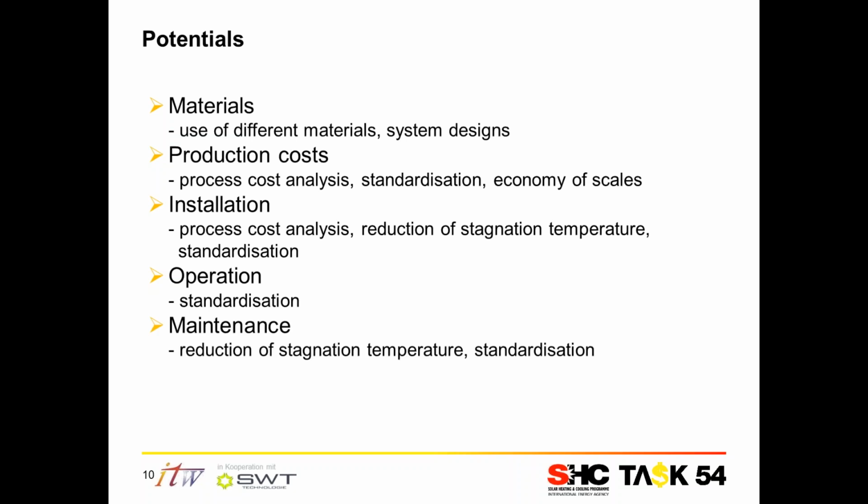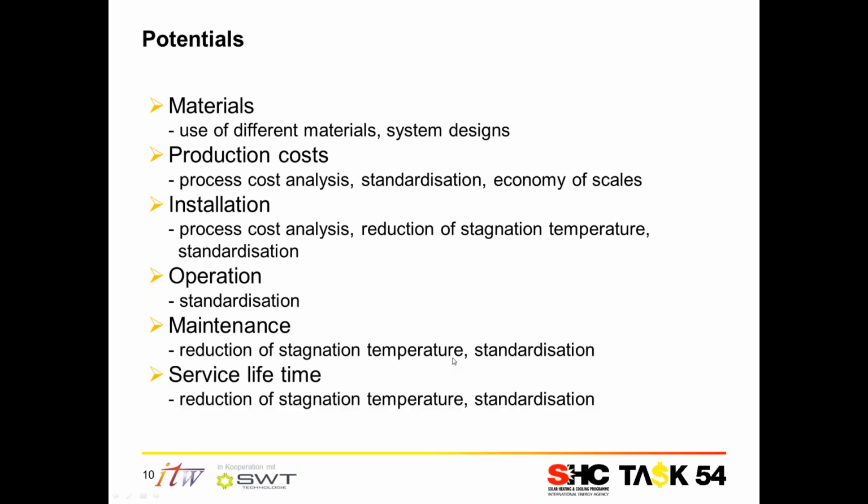The reduction of maintenance can be achieved by a reduction of the stagnation temperature again, and also with standardization, because the installation is error-free if we have a high degree of standardization. And last but not least, the service time life can be extended, which also leads to a reduction of the levelized cost of heat. And here, the reduction of stagnation temperature as well as the standardization helps.